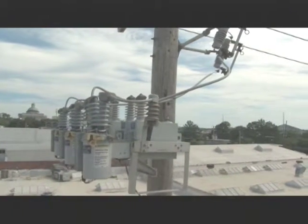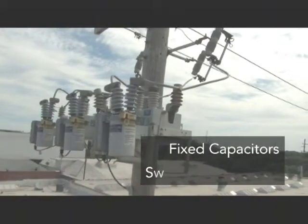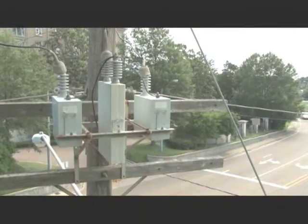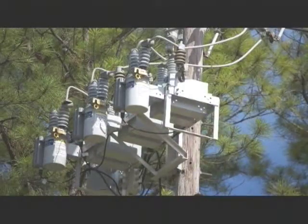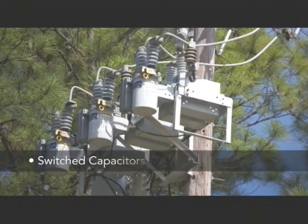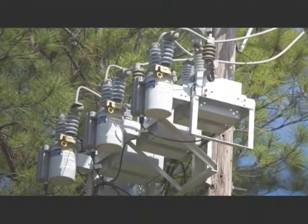Capacitors are normally added to a system in two different ways. One way is as a fixed capacitor. The other as switched capacitors. Capacitors that are connected to the system so that they are always online are called fixed capacitors. Capacitors that can be added to the system when needed are called switched capacitors. Switched capacitors are used to compensate for variations in load current.